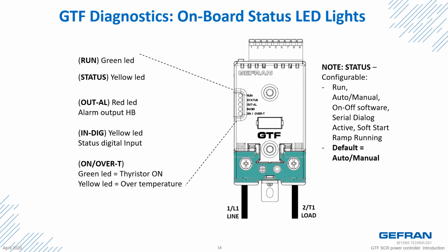The GTF Power Controller has onboard LED lights. These LED lights provide visual confirmation of the GTF operation. LED status indication includes run, auto manual, an alarm condition, the energized or de-energized status of the digital input, the thyristor on state, and an over temperature condition.